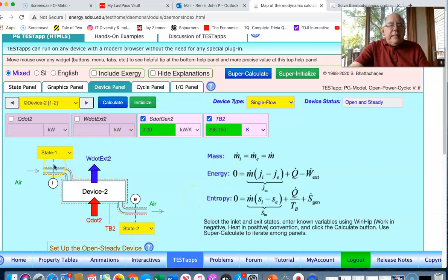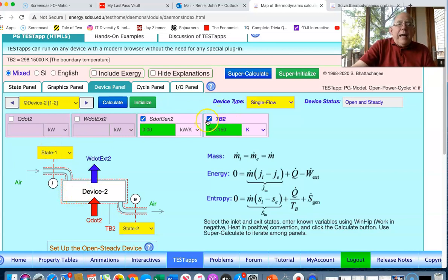Now, before doing that, if I left that undone, this is where we were at. What I haven't done yet, and this is important, is I needed to make sure I added the right temperature, and that's this temperature here, because we know that when this term is equal to 0, the entropy change is related to the heat transfer and the boundary temperature. And so our boundary temperature is 1250 Kelvin.